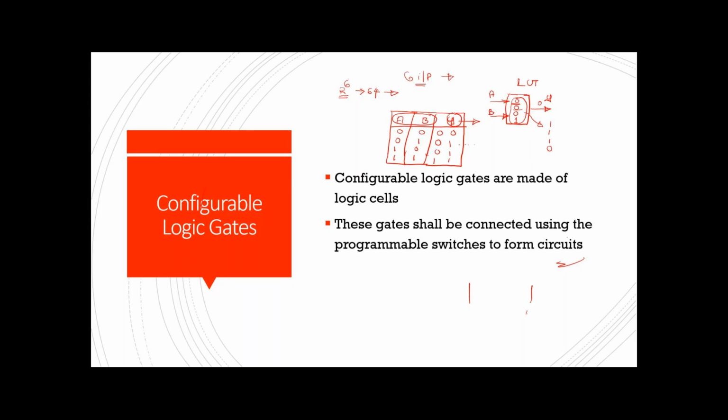And that too, actually, this is one NAND gate, right? And I said 6 input. So if for instance you have another NAND gate, here one more LUT will be there which maybe you make act like an OR gate. And now internally we will have a switching matrix. We say it as a switching matrix. So this switching matrix is also a configurable thing. So if you want to connect from here to here, we basically configure this switching matrix. So this is also programmable so that they will be connected to each other.